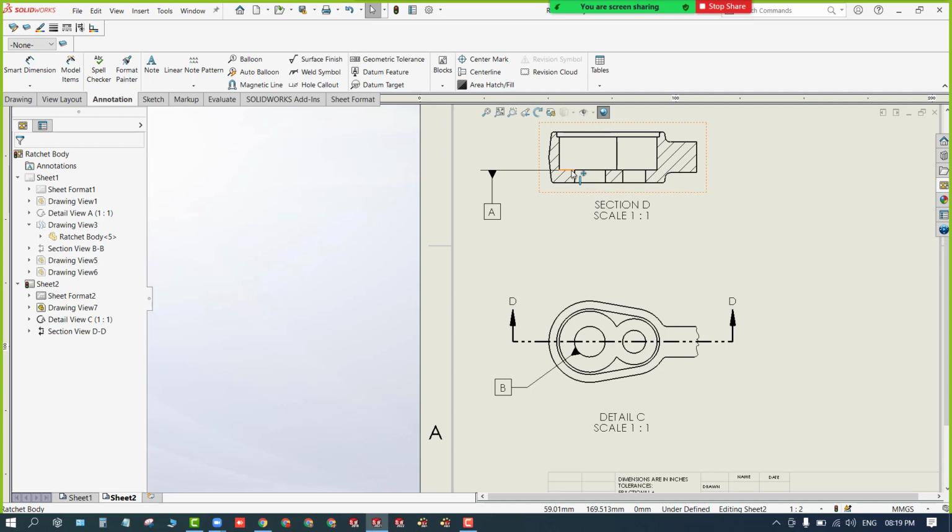Let's say you'll be having a metallic rectangular block. They will tell you to make it exactly 40 by 40 with tolerance 0.01. So for that you need to set two faces as base A, base B. Over there you should not file it or machine it. The reference bases are known as datums. Same thing here, this is reference for me and according to these references I'm going to define the other dimensions.